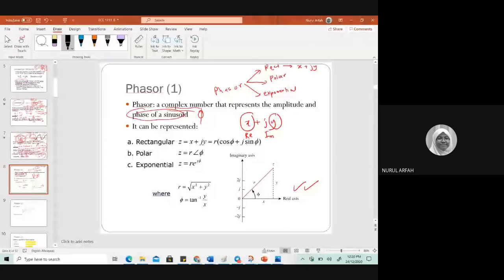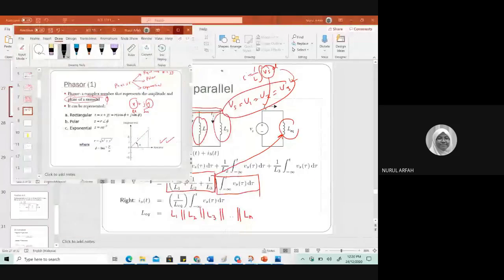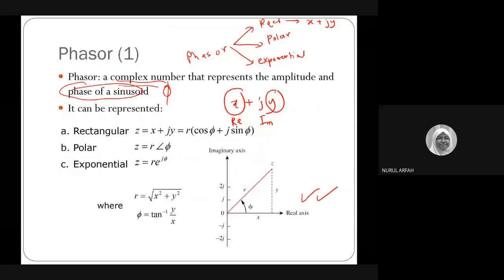The real and imaginary part. So if you plot this, you have imaginary on the y-axis, and then the real axis is the x-axis. Okay, and if you draw this thing, this is the amplitude. The R here is actually the amplitude Vm. Usually they put it as V or I, so they don't want to put it as some signal form like current or voltage, so they put it as R here in your textbook. So just follow that, but you need to know that this is amplitude.